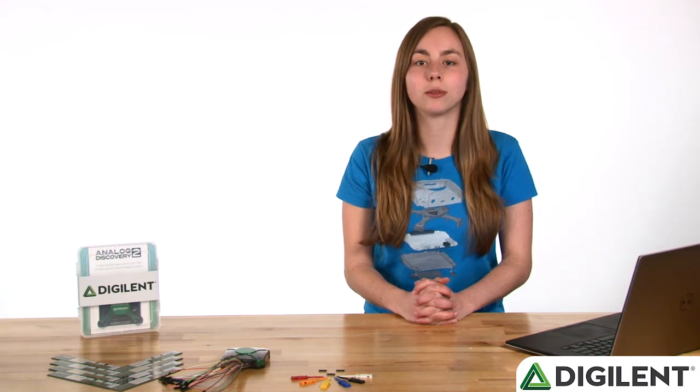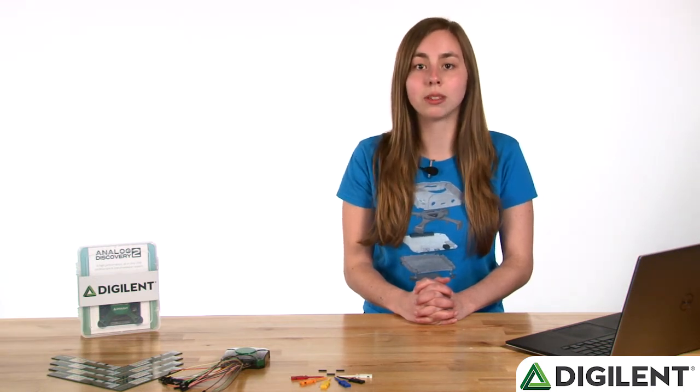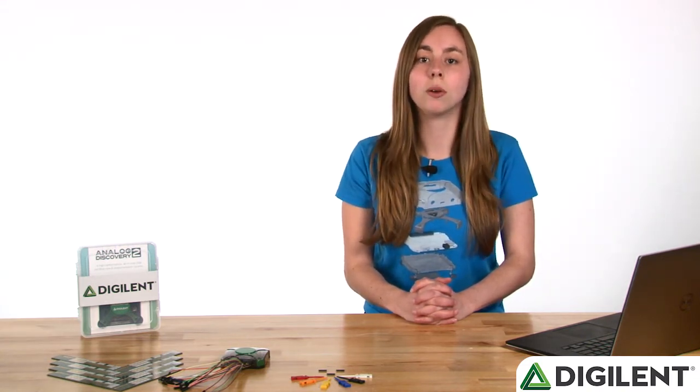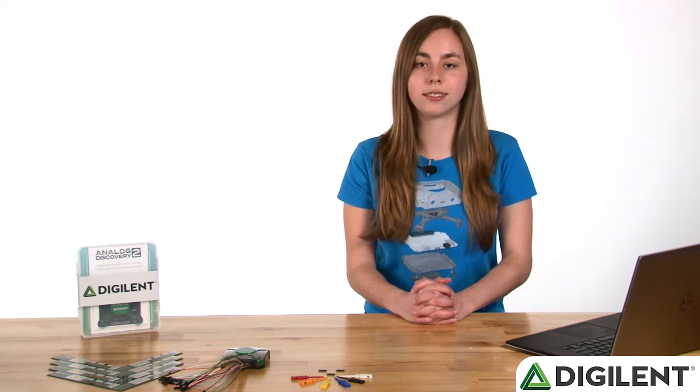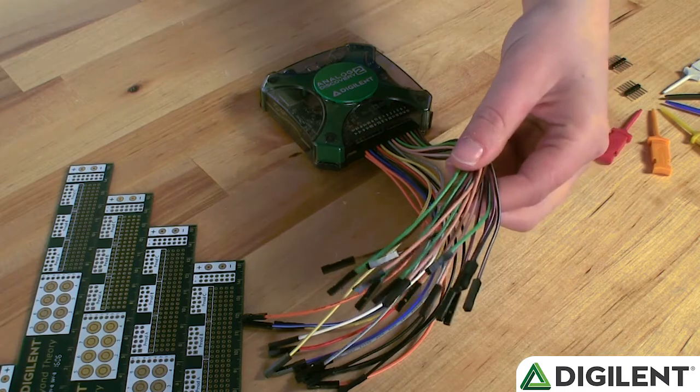Logic analyzers are used to record and analyze digital communication signals. They work in a similar way to an oscilloscope, except the data is processed and displayed with some additional data that's calculated by the software to help with analysis. With the Analog Discovery 2 and WaveForms 2015, you can record and analyze most types of digital communication signals. You can access the logic analyzer through the 16 digital input and output channels.